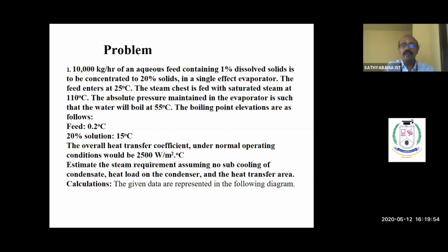The boiling point elevations are as follows: for the feed, 0.2 degrees centigrade, and for the 20% solution, it is nearly 15 degrees centigrade. The overall heat transfer coefficient under normal operating conditions would be 2500 watt per meter square degree centigrade.